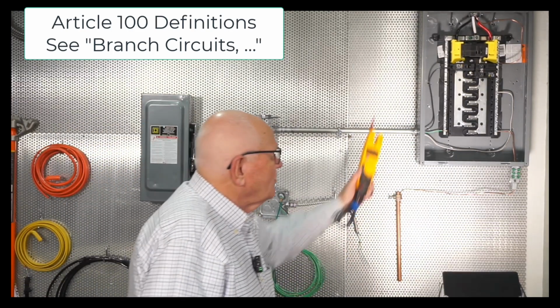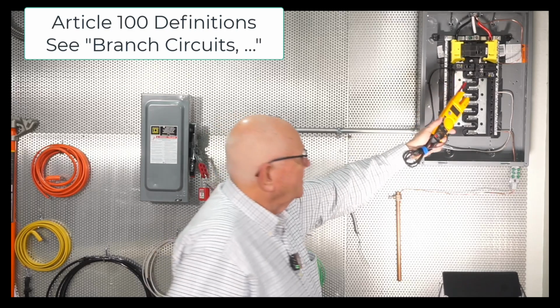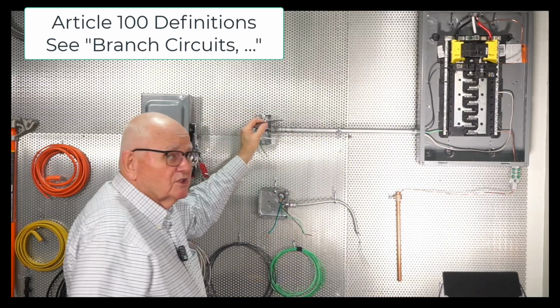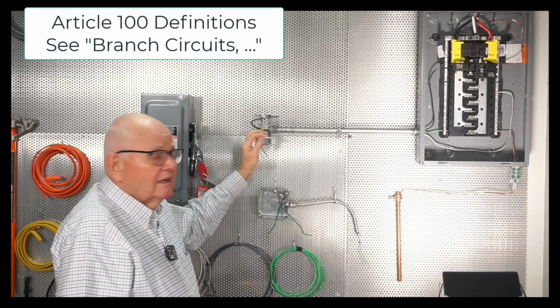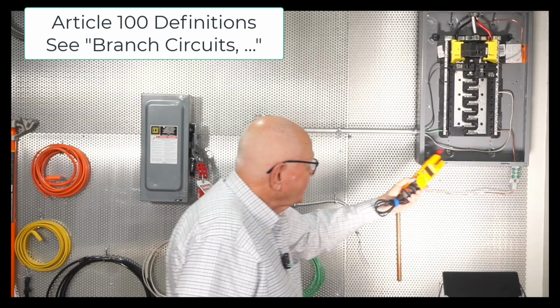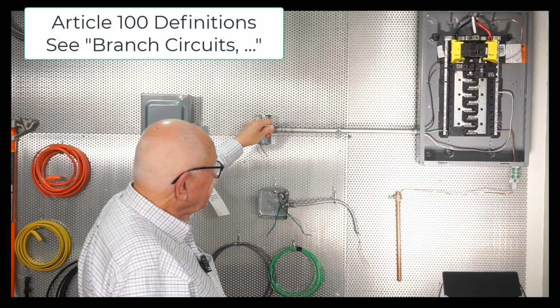Here I've got my panel board, and I've got a 20 amp circuit breaker up here, and through some number 12 wire, the ungrounded conductor, the black wire, is supplying an outlet over here to which I have nothing connected yet, but I could certainly connect a receptacle here. And then the white wire runs from my grounded bus bar inside of my panel board and through that same conduit and comes out here ready to connect to something.